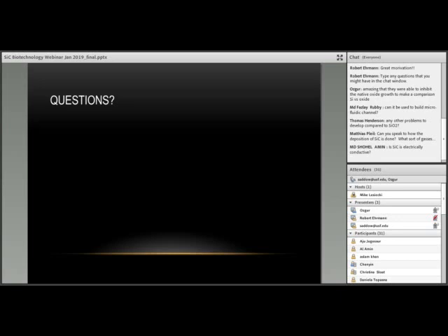Whereas you can etch silicon, gallium nitride, and so on with wet chemical etchants, you cannot really do that in silicon carbide. The only wet chemical etch that works is molten KOH at, I think, 400 degrees Celsius. So pretty much molten salts begin to pit the surface of the material where there are dislocations. So it's extremely robust and impervious to wet chemical etch.